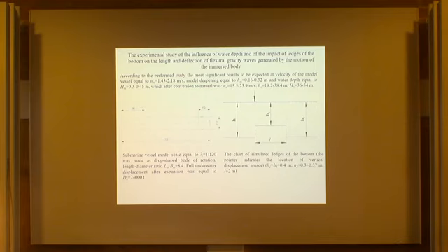The authors have experimentally determined that the effectiveness and failure pattern of ice cover caused by flexural gravity waves generated by the motion of a submerged body near the bottom of the ice can greatly depend on the depth of the water area. In turn, the presence of a ledge on the bottom may affect the wave propagation pattern. This paper presents an experimental study of the influence of the bottom contour on the deflections and the length of the flexural gravity waves.